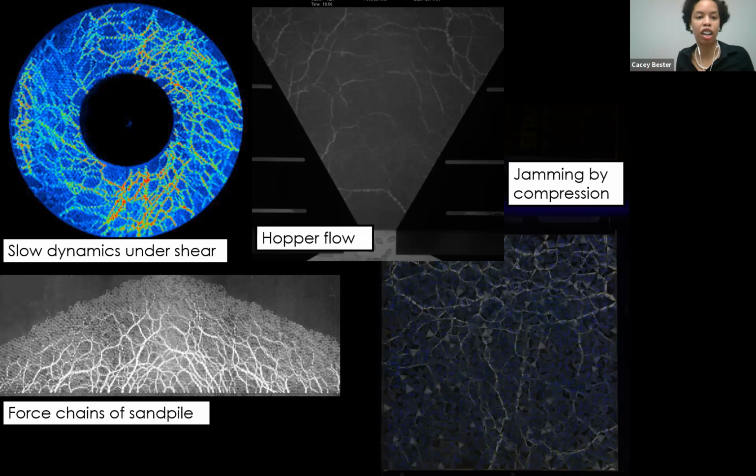If we were to do this type of measurement, say for engineering purposes with regular materials, you'll see that stress propagates smoothly and in a predictable way. But in granular media, as I pointed out, one of the interesting features of granular systems is that the force propagation is nonlinear. So in any granular system, when it's perturbed in some way, there are some grains that will take the bulk of the stress, while other grains take very little stress. And you'll see that in experiments in which we use photoelastic materials to make our grains.